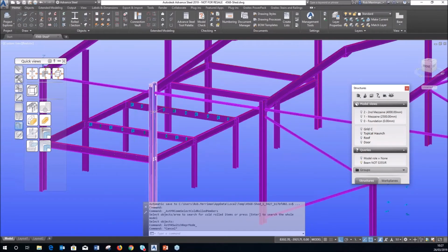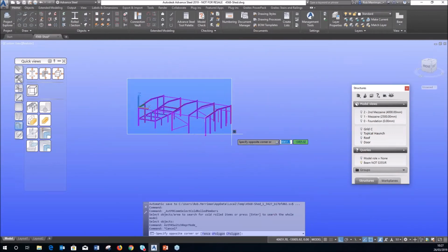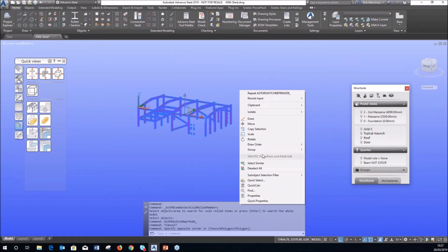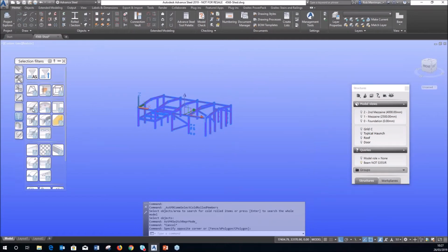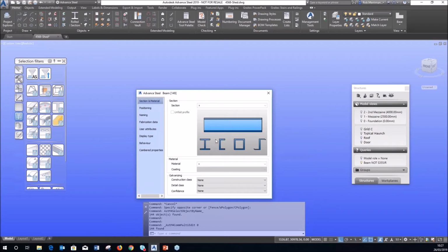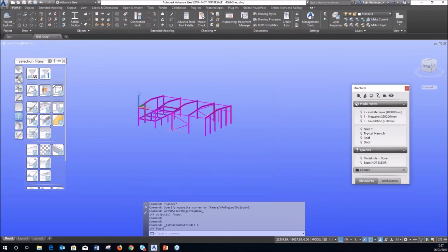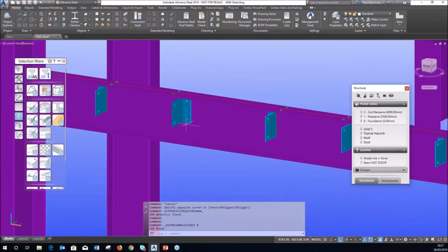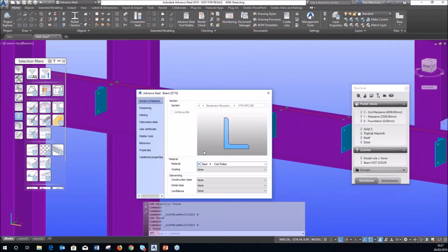So what I'm left with are just the beams, and then I could globally select those beams, use the beam filter, and then I could go and globally change a material. I think in there, because I've got some joints there controlled through the macro.